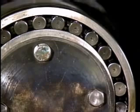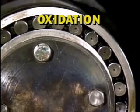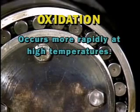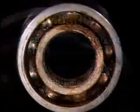This thorough mixing prevents the formation of water pockets that could corrode the bearing. Corrosion can also come from acids produced by lubricant oxidation. Oxidation occurs when a lubricant combines with oxygen, and it tends to occur more rapidly in equipment that operates at high temperatures. The acids produced by oxidation can corrode equipment and lead to lubricant leakage.